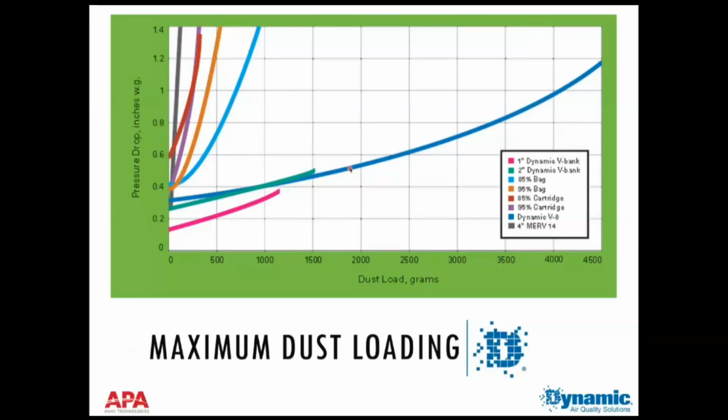On existing buildings, it can allow me to upgrade my filtration with systems that really don't have the fan static and horsepower to otherwise accommodate high efficiency passive filters. And these are the 1 and 2 inch V-banks.